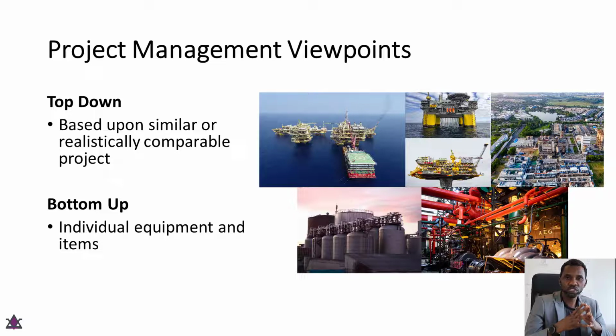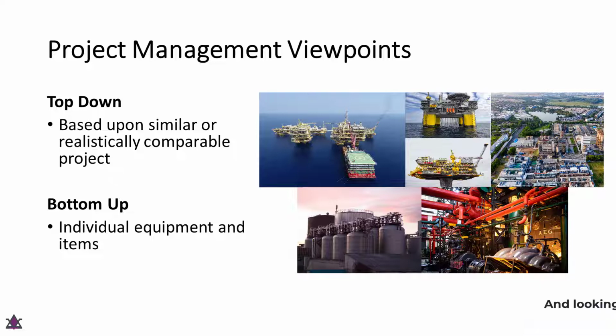So this is also explained in this picture, where you have the top photographs showing an industrial facility and offshore exploration facilities. That's a bird's eye view, because there are so many components that you cannot pick them one after the other. But looking at the picture below, where you have a more controlled environment, you have vertical vessels, storage vessels, pumps, and pipes, all of which can be estimated. So looking at a detailed level is the bottom-up approach, and looking at it from a bird's eye view is the top-down approach.